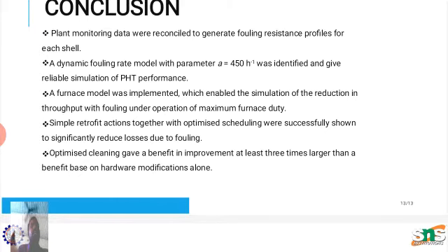Crude refinery preheat trains are a major part of the refining process, as these units reduce the amount of thermal energy required to heat the crude oil to its distillation temperature. Fouling is a long-standing problem in the operation of preheat trains. The ability of a refinery to process different crude blends or to increase its production capacity depends on the thermal and hydraulic performance of the preheat train under fouling conditions.